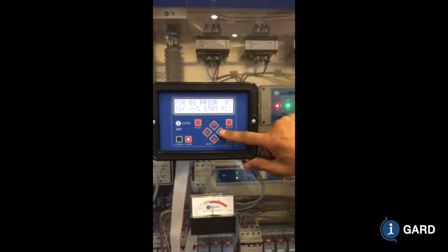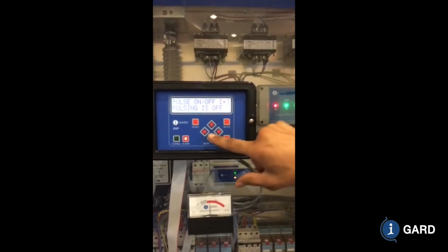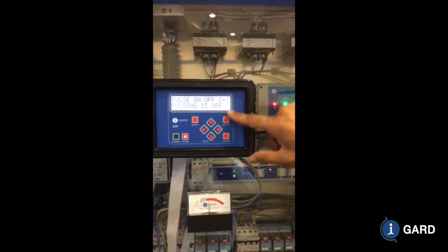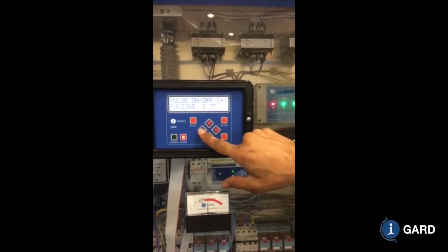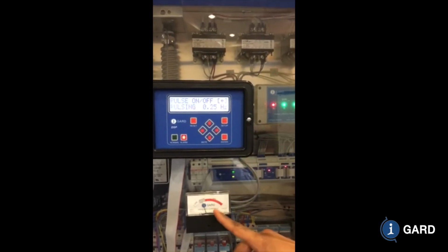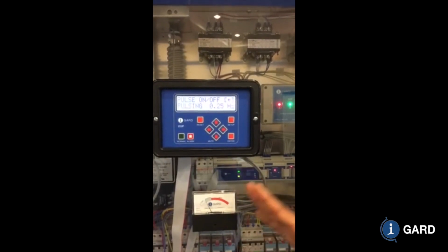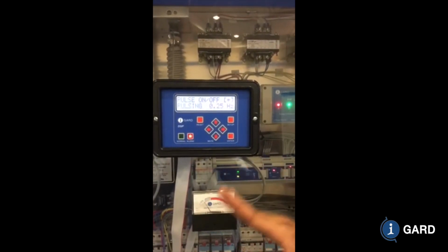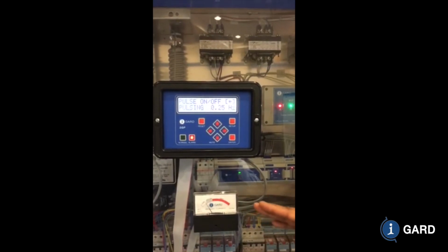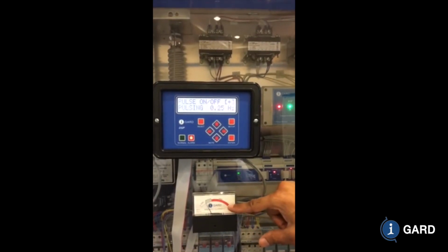We're at 100% now. So if I go to turn pulsing on by going 1 over to the pulsing page, hitting the left button, that turns pulsing on. And notice that what we're doing is we're changing the fault current from 100% to 50% once a second. This pattern is what we're going to look for.